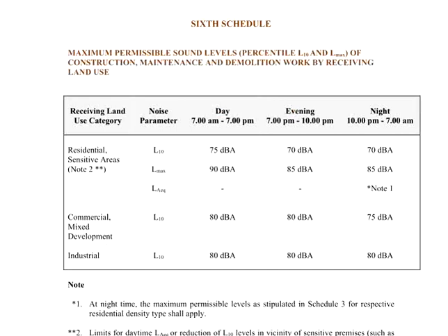During the constructions, there may be project activities bringing the noise, and therefore the 6th schedule shall be referred. Some of the work, such as pile driving, can easily generate the noise beyond the limits. Therefore, you might need to work out the mitigation measures in order to minimize the noise or to protect the workers from the adverse impacts due to the noise.